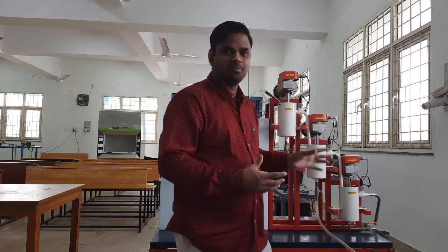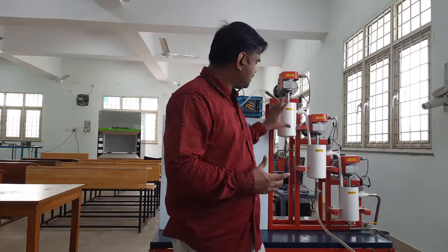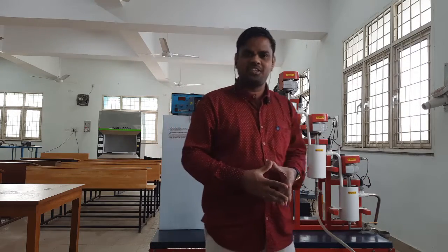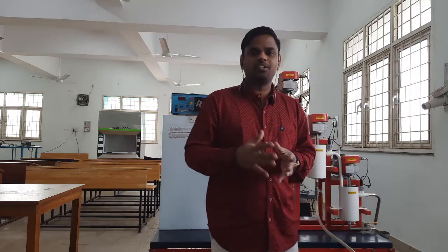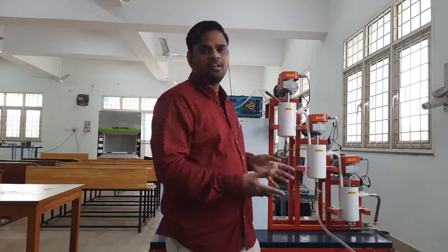The aim of this experiment is to study the performance of the saponification of ethyl acetate with NaOH in a cascade reactor system of CSTRs, wherein we have 3 equal volume CSTRs in series. And we will prepare a performance chart or a table where we compare the performance, that is, what is the conversion in each reactor. So we will be preparing the performance chart for this reaction system, and we will determine the reaction rate constant at the ambient conditions, that is, at room temperature.